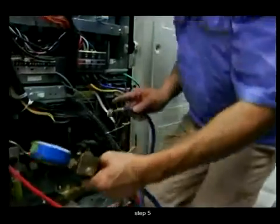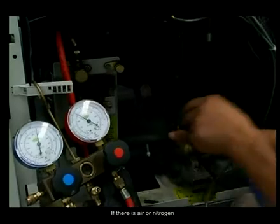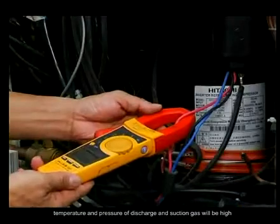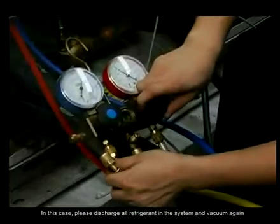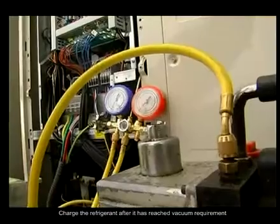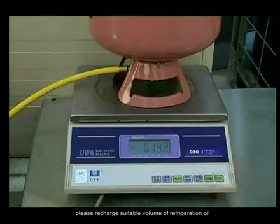Step 5. Use refrigerant pressure gauge to check if there is air or nitrogen in the system. If there is air or nitrogen, temperature and pressure of discharge and suction gas will be high. Current will be large, and the pointer of the pressure gauge will shake. In this case, please discharge all refrigerant in the system and vacuum again. Change the refrigerant after it has reached vacuum requirement. If refrigeration oil goes out during the process, please recharge a suitable volume of refrigeration oil.